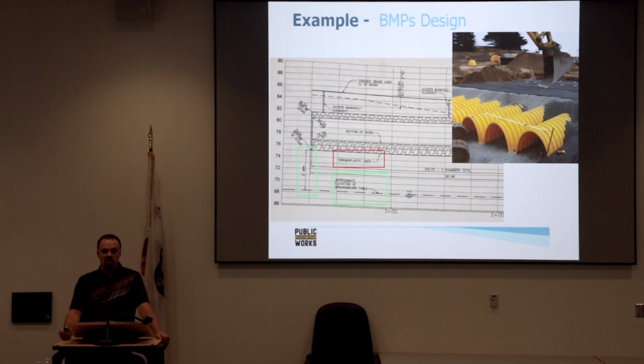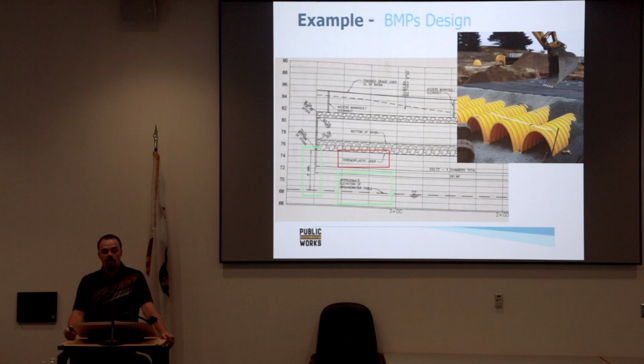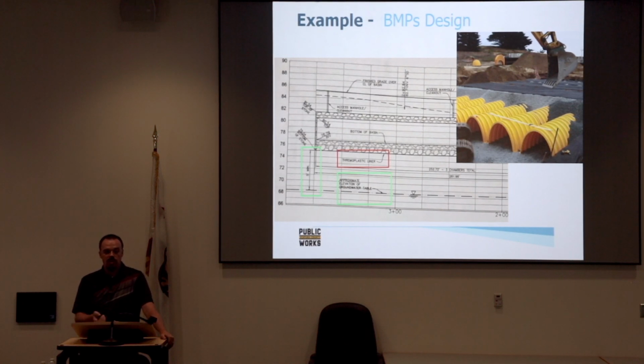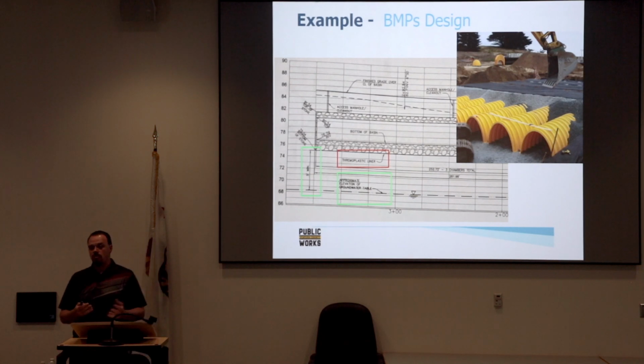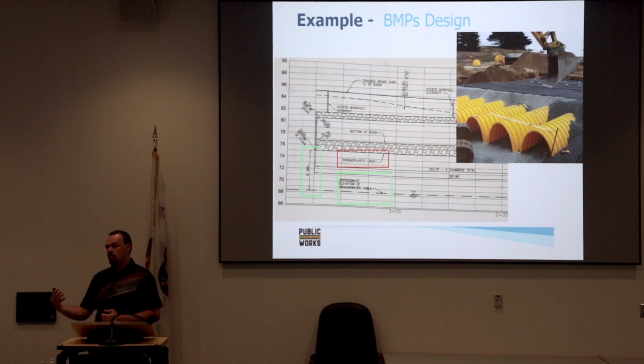So just a simple little addition to the design here. What I'm guessing occurred here was the engineer did a great job structuring the site, how everything's going to drain, put this in there because they probably checked a standard detail on the vendor's list, and the vendors purposely make these systems to be used for infiltration or detention to expand their markets. So they obviously looked at the wrong detail and put it in here.